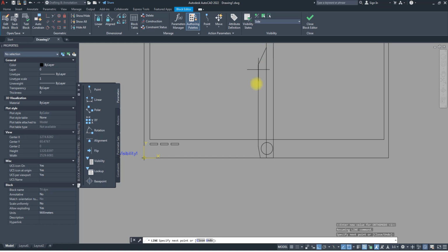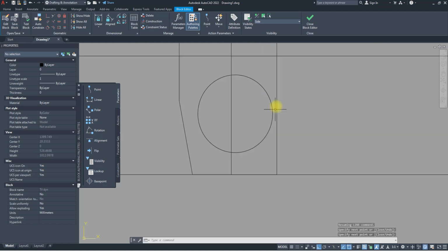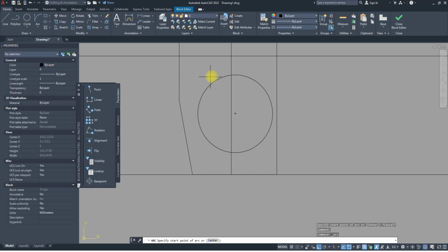So let's say this. Then this button, I want to create a button here. How small do you get now. So I'll just use my arc, A-R-C for arc. So let me just come to my home tab. I want to use my start, end, direction. So my start is going to be on this point.